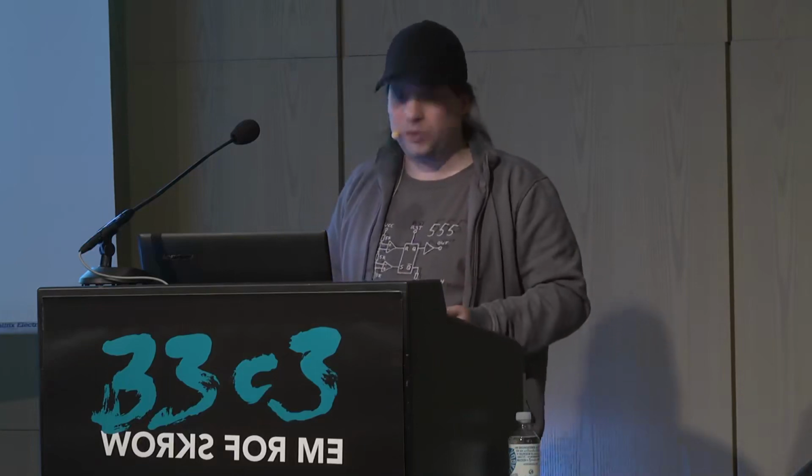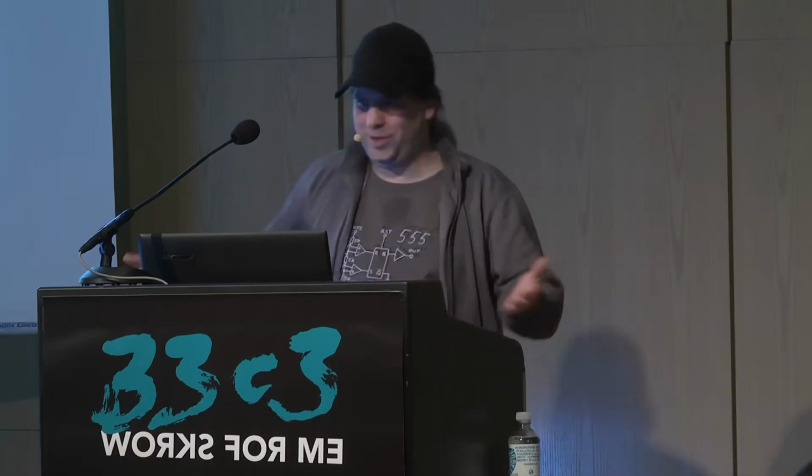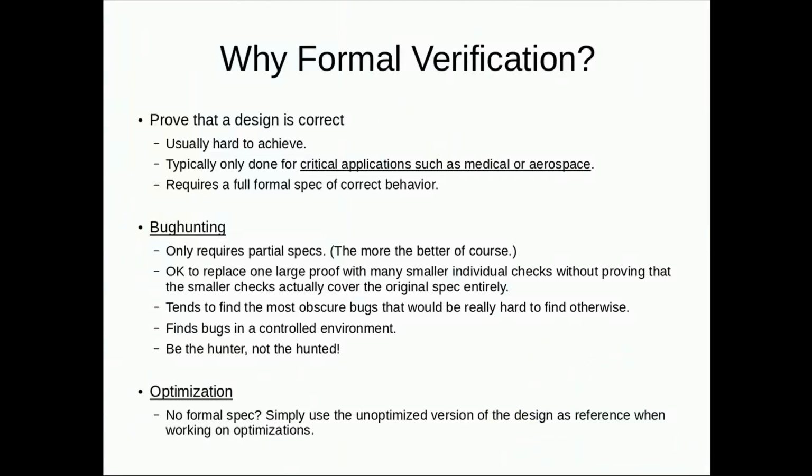But if you find the same bug with a formal tool, it will give you a counterexample. It will tell you, well, if I use the inputs of your circuit in this way, then the circuit will go into this state, and here you have said this state is an invalid state that should not be reachable. So you're in a much, much better position to figure out what's actually going wrong. Even if you could already reproduce the bug in hardware, you would be on a very different standing here. So be the hunter, don't be the hunted when it comes to bugs.